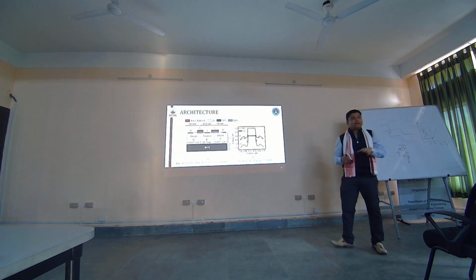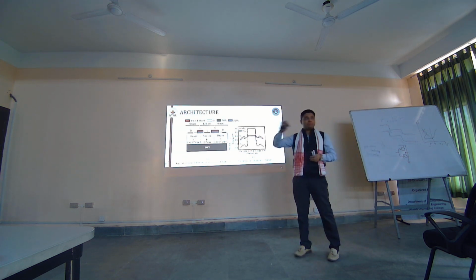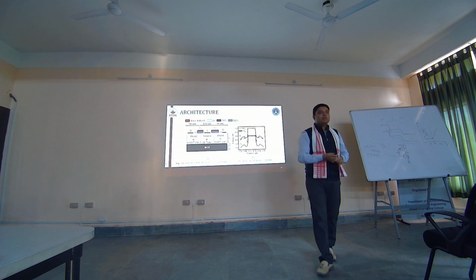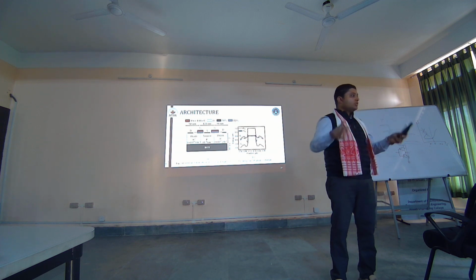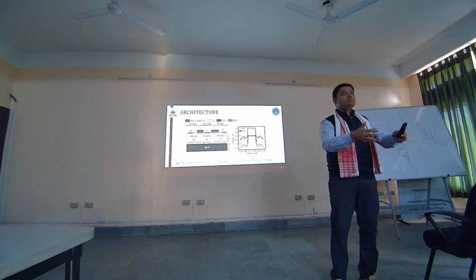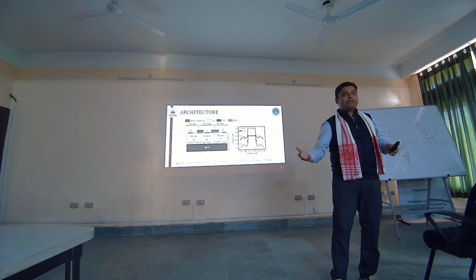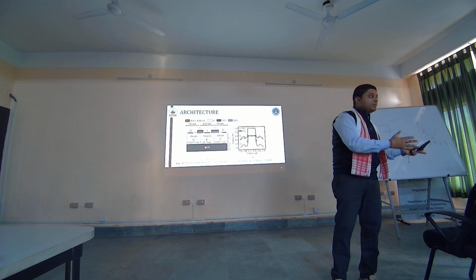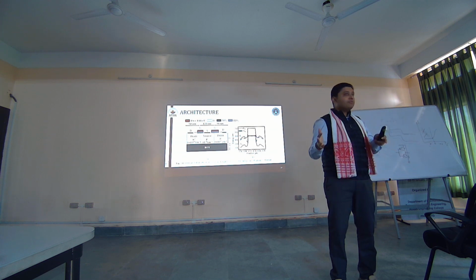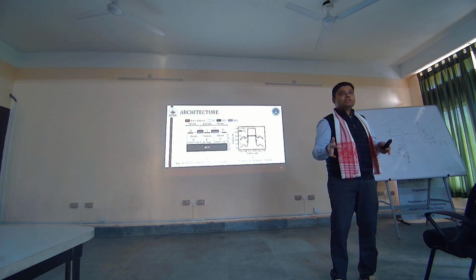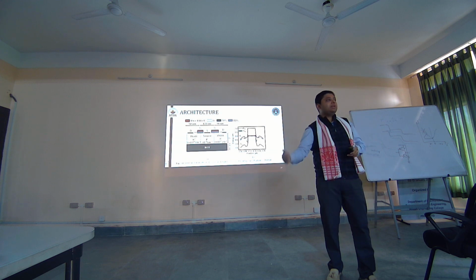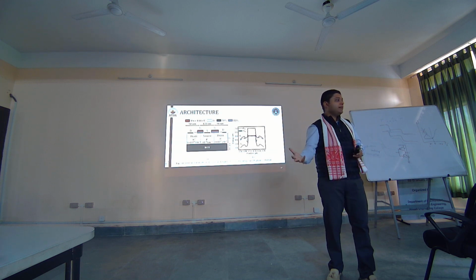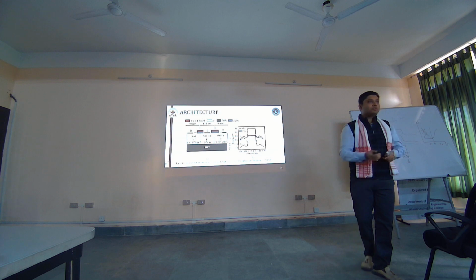The answer is that during that period or era which we are talking about, you could not have technology which could apply lower voltages in your devices. Your device area was very huge, right? You needed to think about the breakdown voltage of your device. So PIN devices had very good breakdown voltages compared to PN junction, tunnel diodes. Therefore, PIN tunnel FET became the basis for the conventional TFET instead of a PN TFET.